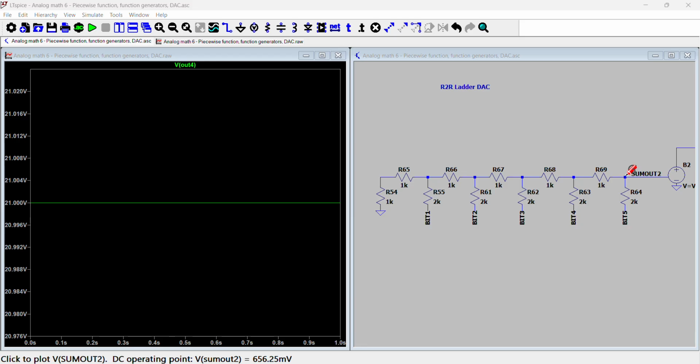And actually, the reason for that is because what's happening is they're averages. So when you have two voltages and they go through a voltage divider and there's a voltage output in the middle of the voltage divider with the two voltages at both ends, this is basically a voltage average, right? So essentially, because of the way it's set up, it's averaging all of the contributions, but then ends up multiplying by the number of contributions again. And this is actually the genius of the R2R ladder. Unfortunately, I can't show math on here, but when you work it out, that's exactly what's happening.